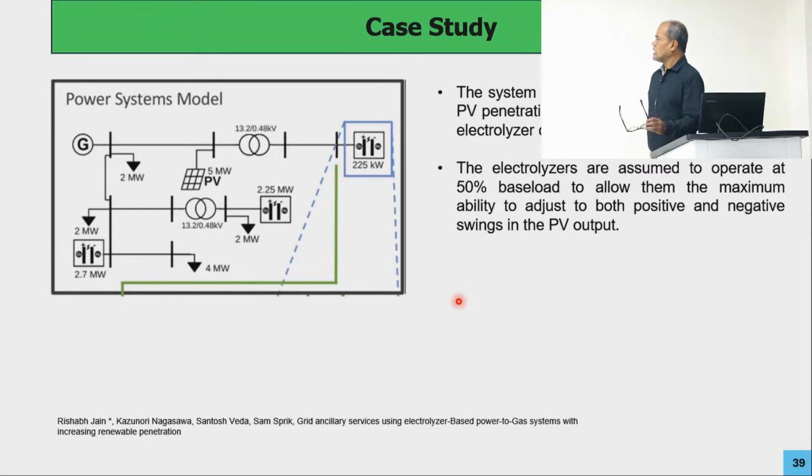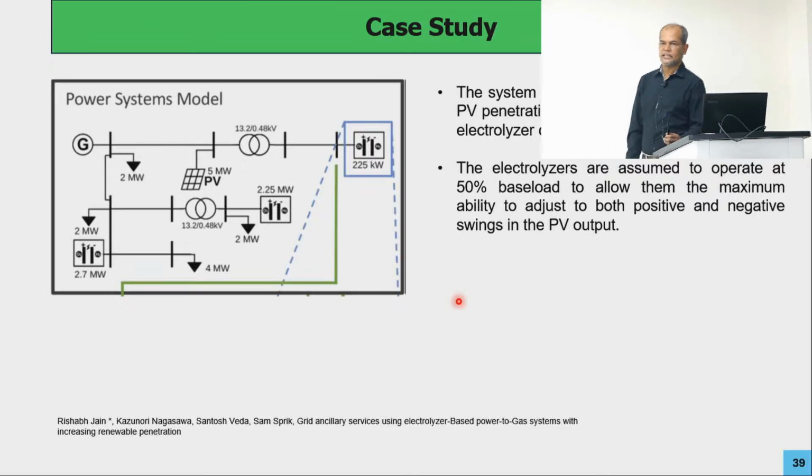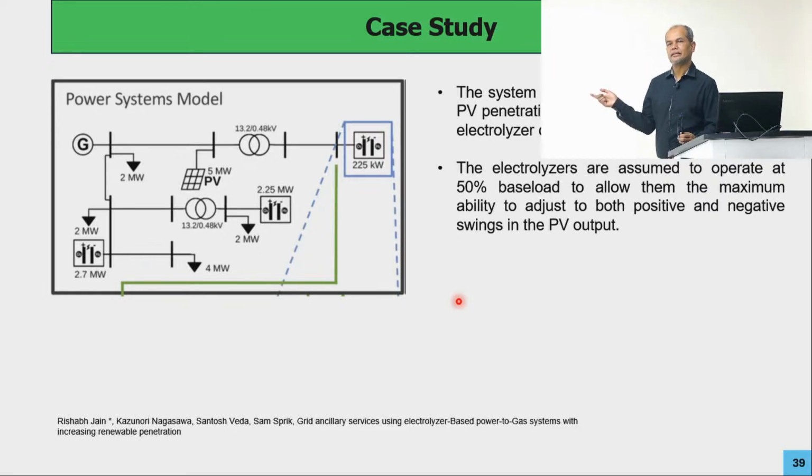So if something is relevant to the demand side, the load, the electrolyzer, like one of the examples that I showed previously, that can actually provide a good service. But let's say some problem is introduced by a synchronous generator, for example, a small signal stability problem. In that case it is found that the electrolyzer cannot contribute to reduce the oscillation that's coming from the synchronous generator.